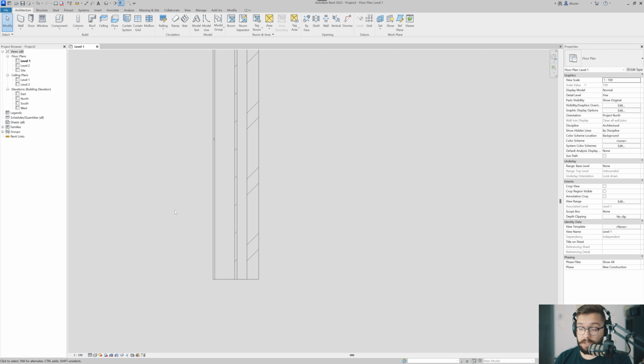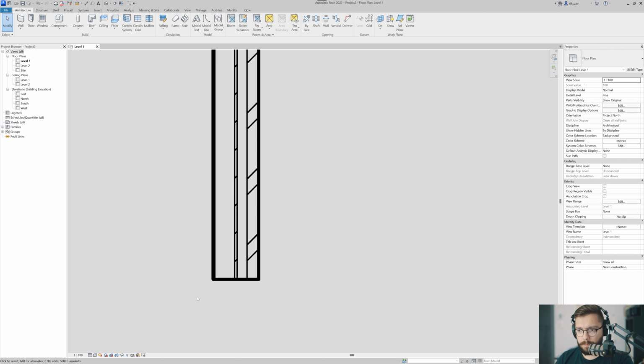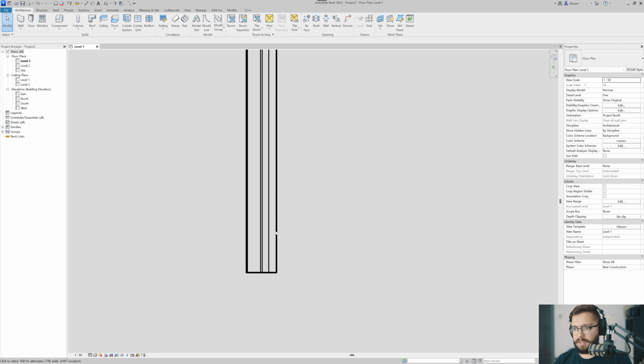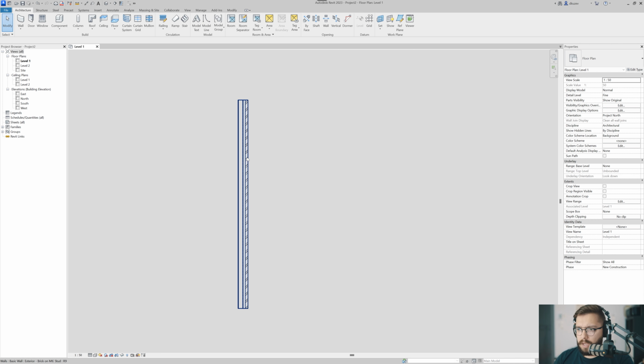If you want to see some of the line thicknesses, TL is the shortcut you're looking for. So TL on my keyboard gives me this. In general, I don't like working in a scale 1 to 100. I would go to 1 to 50. It alleviates a little bit of that line weight thing. But line weights are something to talk about in a completely different chapter.